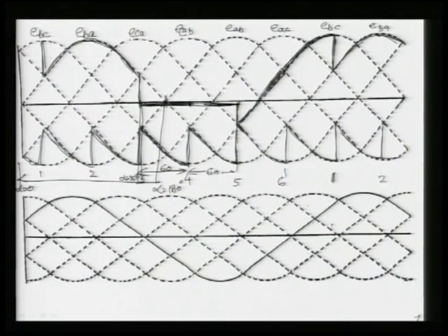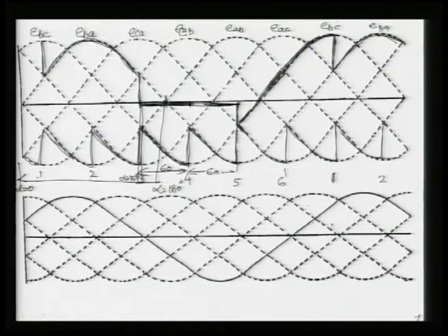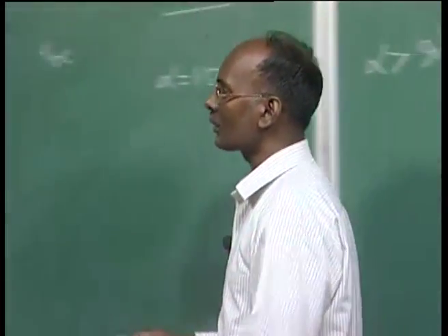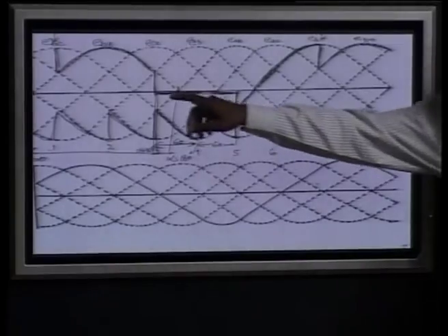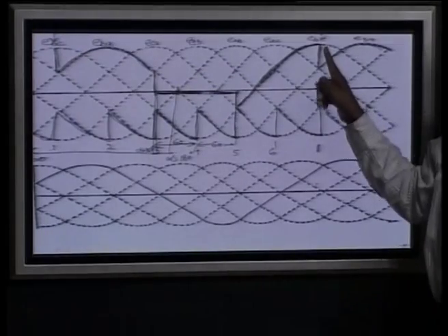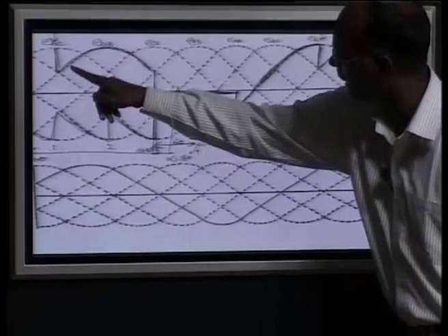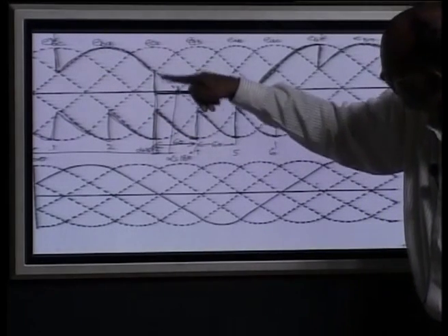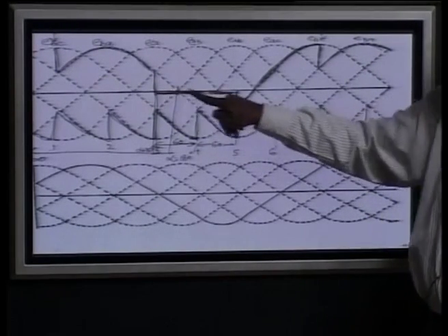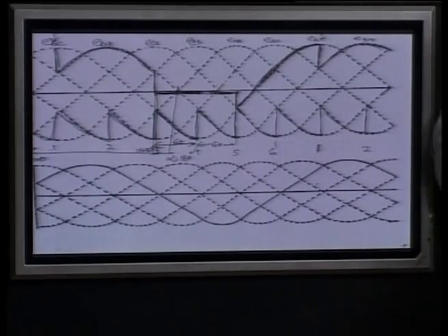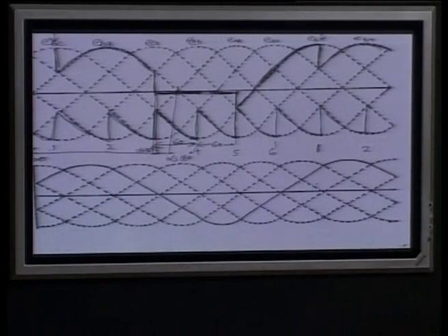You see, because 1 was fired here, 2 firing will not affect anything, because the voltage will be the same. Now, EBC you can see starts from here, just where we started. So, it is a complete cycle. The valve voltage you can see here, it was coming here EBC, and again the cycle is completed. So, EBC suddenly here, now EBA is following. Once 3 is getting a pulse, suddenly it is 0 and then it continues, and this is your voltage. So, this is valve 1 voltage.